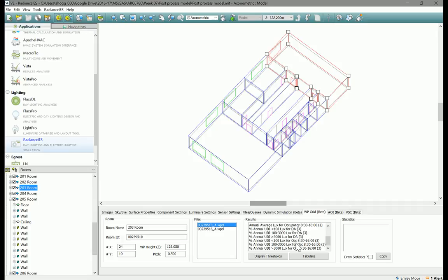We had 144 different times in the year, and then we maybe have 100 sensor points. So we've already got about 144,000 individual illuminance readings for each of those points, for each of the hours that we tested. If you then tested for the whole year, then you've got more. You've got 365 days, you might have on average 12 hours per day, and then you might have 100 sensor points. So clearly it's a lot of data.